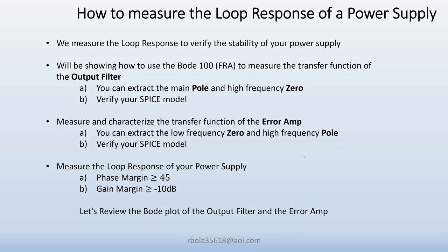In this video, I'm going to measure the loop response, and one of the reasons that we do that is to verify the stability of your power supply. That's one of the biggest things: if you don't design your compensation specifically, then you're going to have instability. You might have oscillations. If you measure the loop response, then you can verify that you're not going to have any conditions where it's going to oscillate.